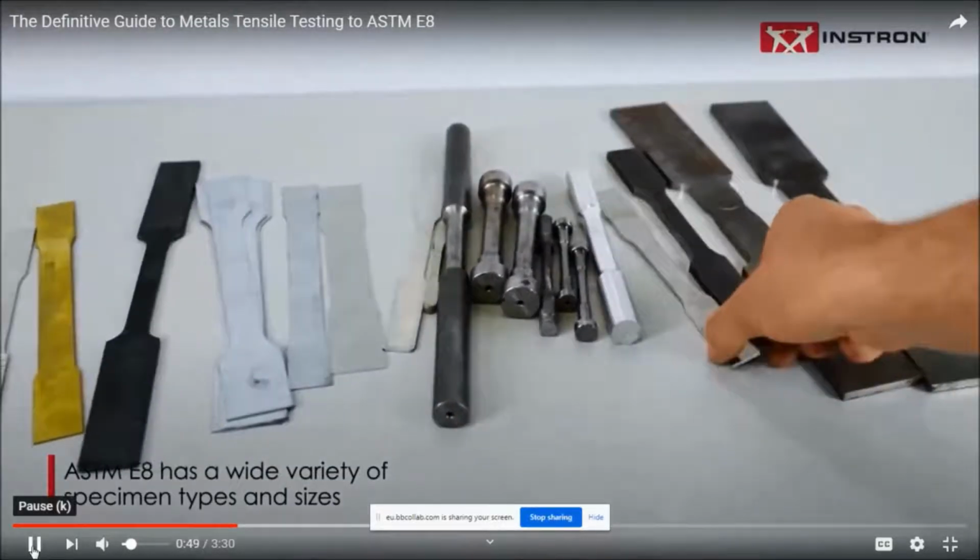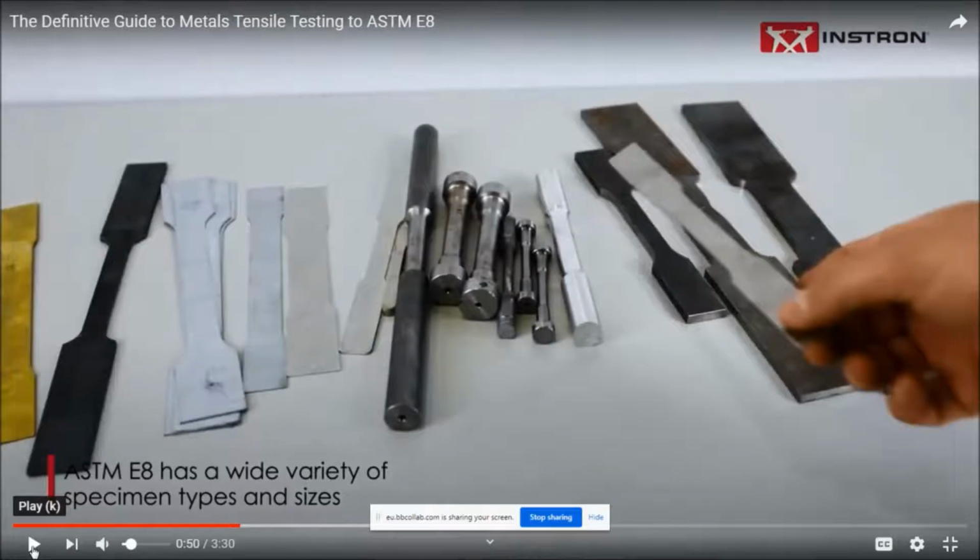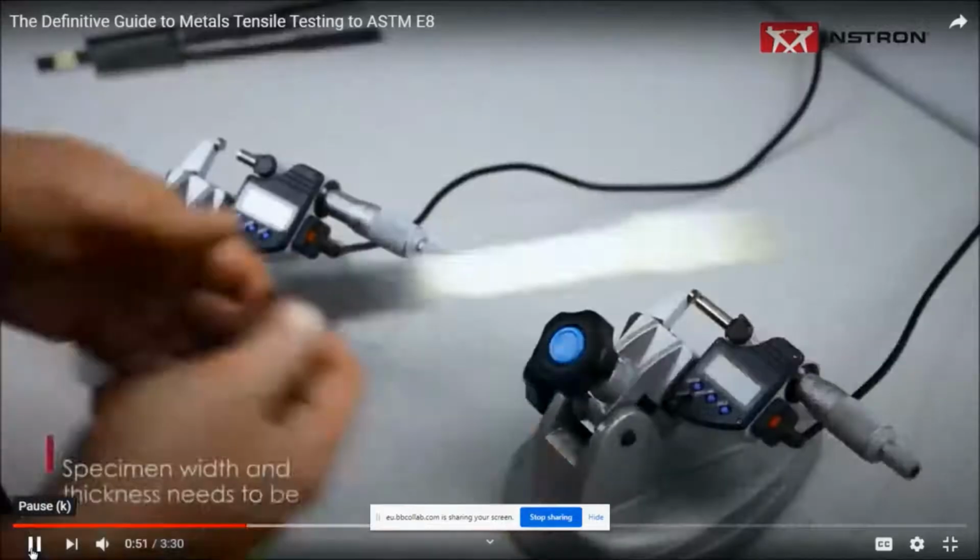Here you can see a couple of test specimens. You may notice that some of them have different shapes. Some of them are flat, and some of them are rounded, or they have an axisymmetric geometry. It depends very much on the kind of machine that you're using and the kind of material that you are testing, right? The shape, the size, the thickness and the width of these test specimens are very well defined in industrial standards, like this one, ASTM E8, which in this case is for metallic materials, right?